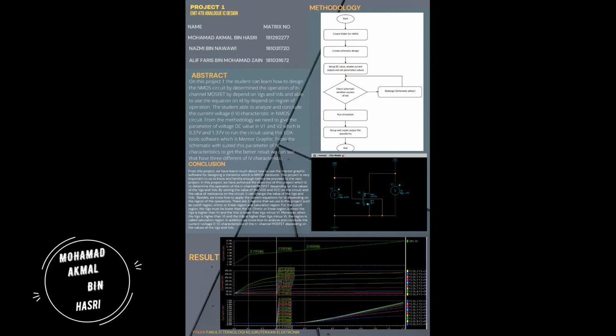Okay, now I will explain about the methodology. First, we create the folder of the NMOS. Then we create the NMOS circuit. Then we check the circuit whether there is an error or not. Then if no error, we simulate the design. Then we obtain the waveform.